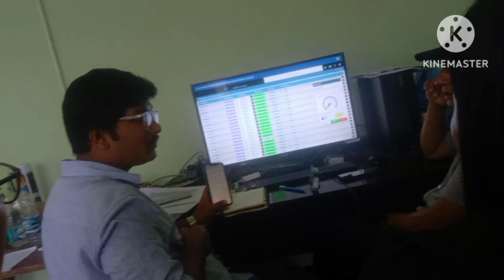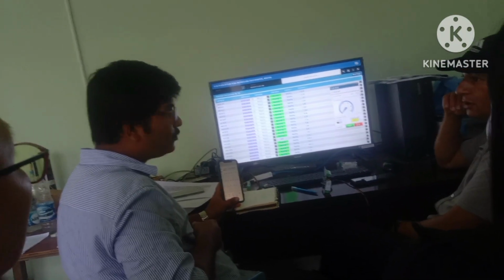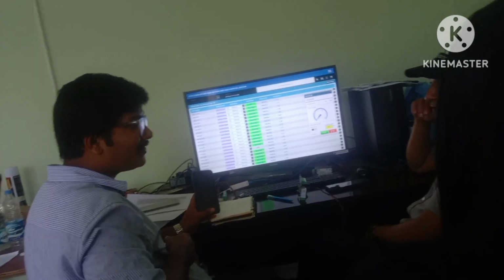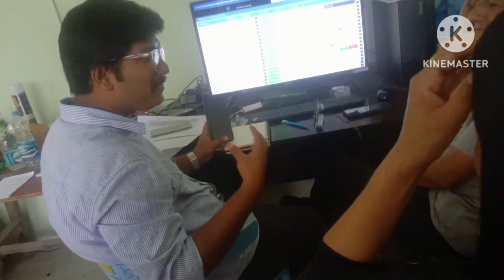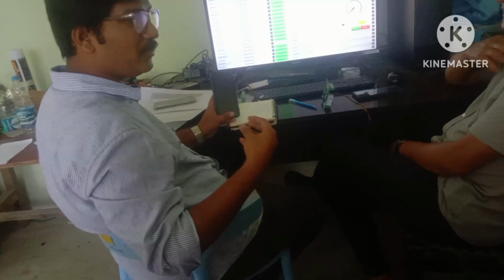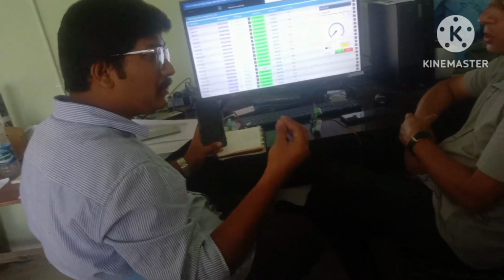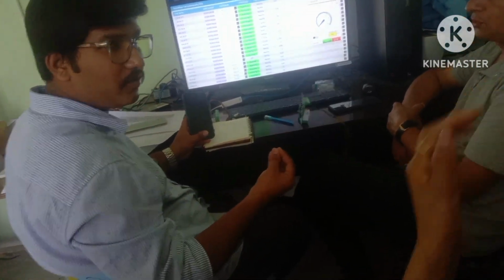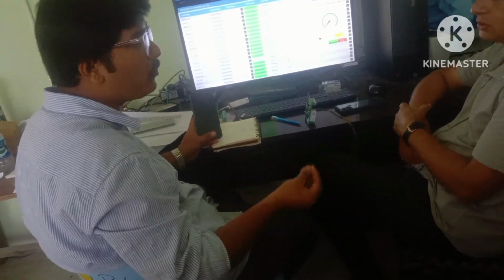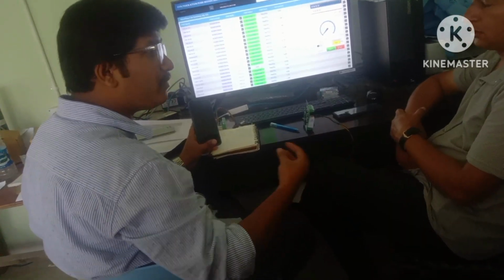Digital. But digital what? Input or output? Output. You are giving someone a command, so the action is someone's input and your output. So if you are giving any command, just to turn on or off, that is digital output. And I am getting some feedback from that device.